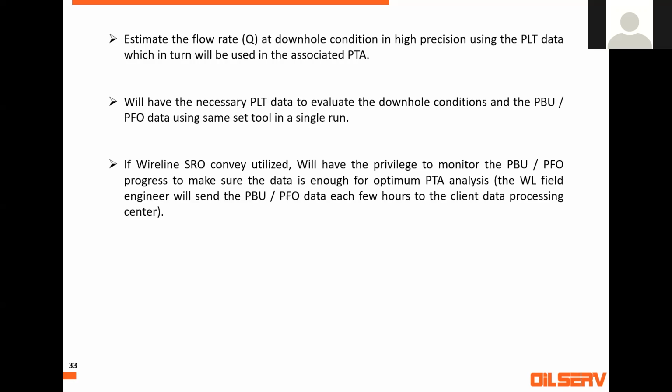With a memory tool, they need to guess based on their field knowledge. They say, okay, make the buildup for 2 days, something like that. But when they have wireline, they can monitor in real time. The field engineer will send by email the latest file every 2 hours to the processing center of the client or the final user, and he will monitor the PTA.